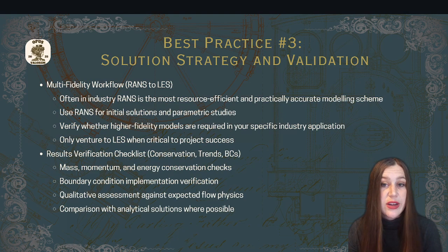When working in industry, RANS is the most resource-efficient and practically accurate modeling scheme. So these models are used most widely. You should first verify if higher fidelity models are required in your specific industry application and only venture to LES if the project success depends on it.